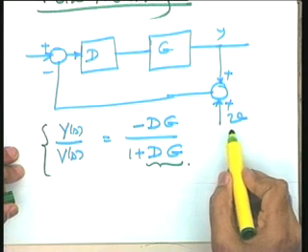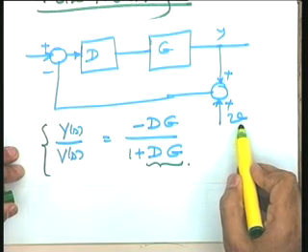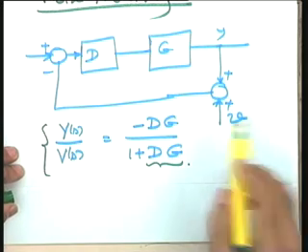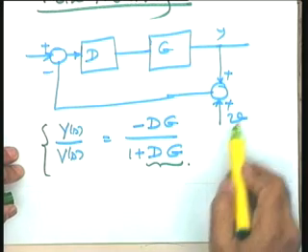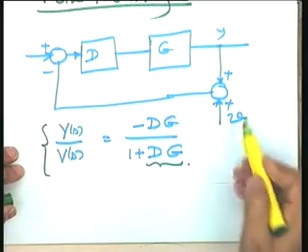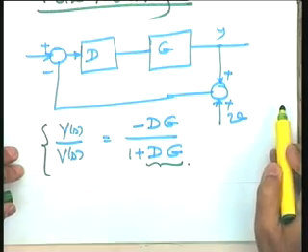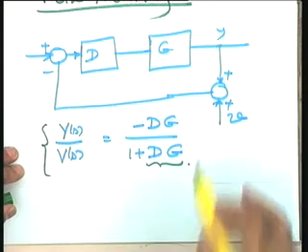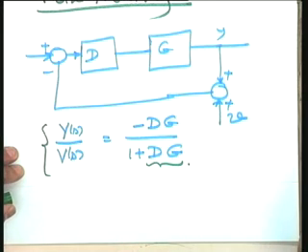So it means we take care of the noise problem by introducing an additional component, an appropriate high frequency noise filter, so that this particular noise, the high frequency noise, is blocked by that particular filter and it is not allowed to enter into the loop gain. This will permit us to go for high loop gains for disturbance reduction and sensitivity reduction.